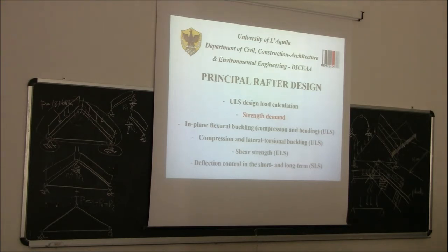Once we accept and understand that the sum of the solutions of those two structures is equivalent to the solution of the original structure. In other words, when you have a structure, you can always add, if you want, a restraint, solve this structure, and then superimpose the solution with another structure where we have applied the opposite restraint reaction. Okay? So it's okay. Do we have any doubt about this? Are you convinced, or do you have doubts about what we've done here?